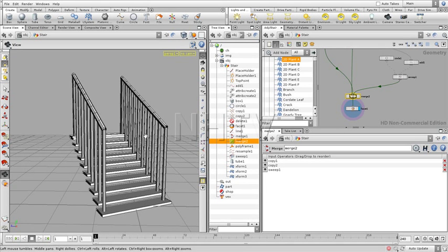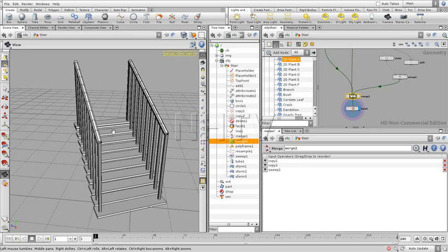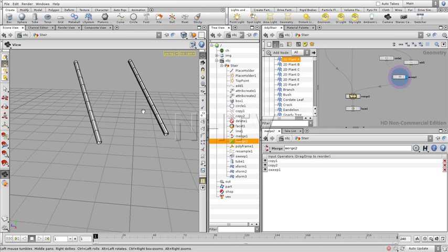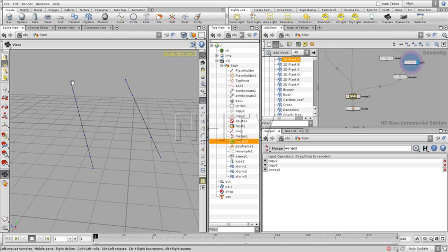This is all fine, except for one thing, which I still don't like, is that normally you make these parts just a little bit longer. They're just very short over here. So we're going to increase their size. Now for that, we're gonna do the following. We have these lines. What I'm going to do is create normals which are either pointing towards each other or pointing away from each other. It doesn't matter that much really. And I'm gonna move those points later on following the normals.